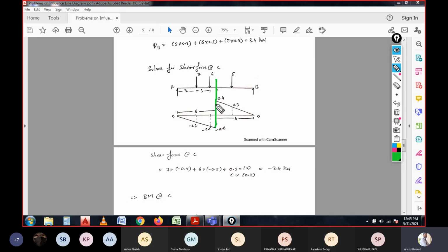So in this section we need to have the shear force diagram. For this shear force diagram, it has been calculated by considering the similar triangles over here, like this, right? In this similar triangle, the loads are acting at particular distances. So those loads are to be considered, which is for the calculation of the coefficient values.